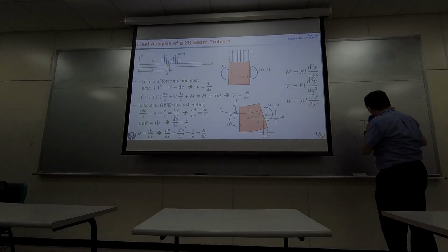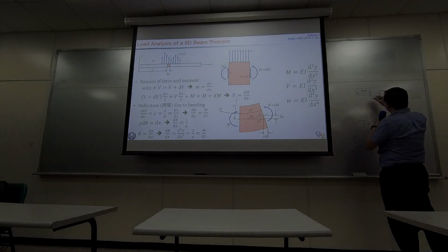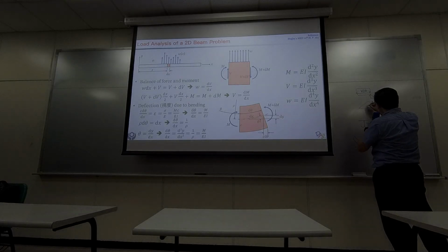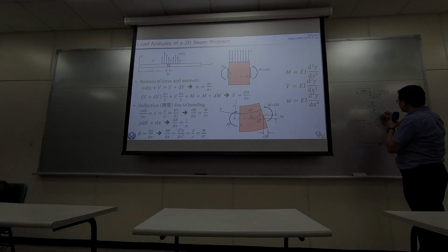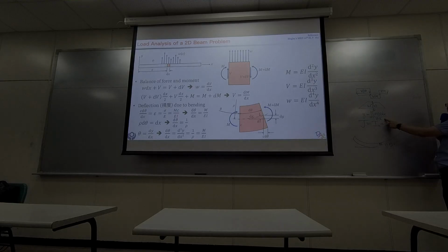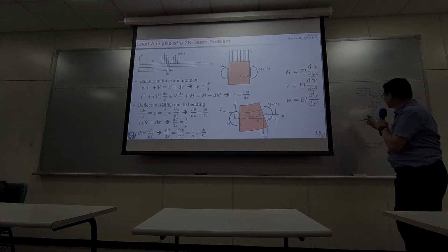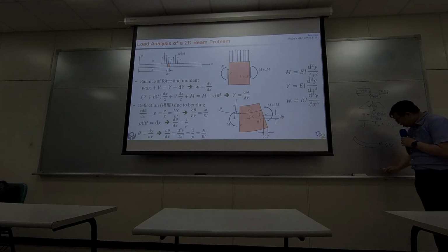So later on, usually what we are going to do is, for a beam with certain conditions, we will figure out the shear diagram. So shearing forces, right? We have shears everywhere. And then you need to figure out the moment. Once you have the moment, you can take the double integral of moment, then divide by EI, and you have the deflection. So you can figure out what Y will be everywhere. You know how the beam deflects.